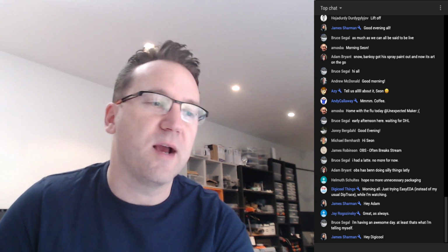G'day Greg. Just trying Easy EDA instead of my usual DipTrace while I'm watching. Cool. Easy EDA is great. Like it really is for a web tool, and with the integration into LCSC and JLCPCB. I've been tempted a couple of times. Only a couple. It's got some gotchas, like you've got to be careful about. Sometimes the DRC doesn't find things, like you can have a trace through a copper fill incorrectly and stuff. And you've got to be very careful. But once you work out the nuances of it, I think it's actually probably a really good tool. I'm tempted because of the panelizing in it.